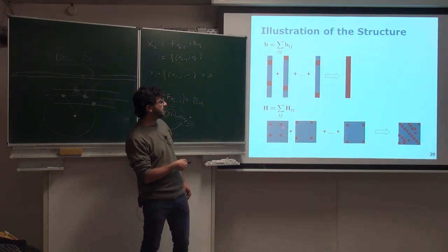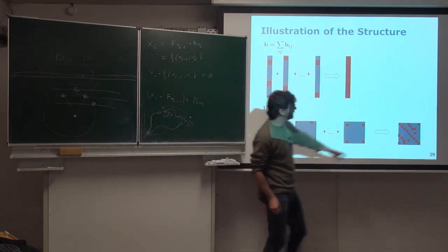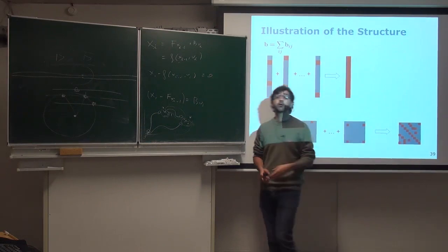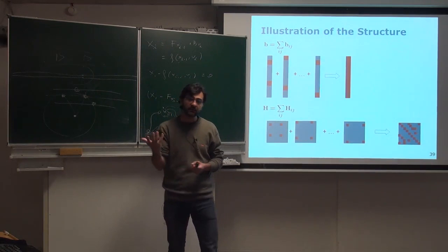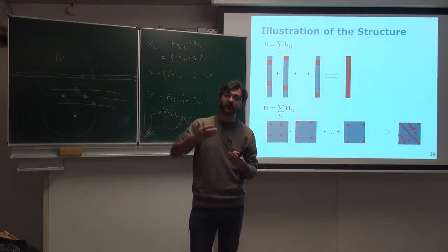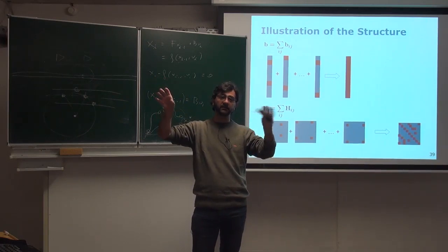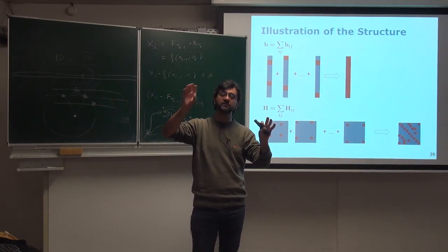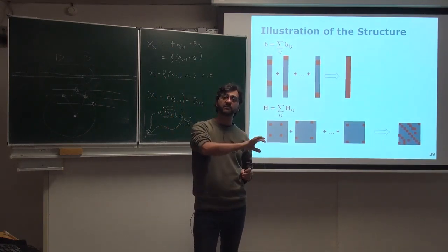What we end up with is a very sparse structure, and the interesting thing about this structure is that every off-diagonal non-zero element corresponds to one edge in the graph. Okay? And that's the relation between the concept of graph-based SLAM and least squares: the adjacency matrix of the graph actually has the same sparsity structure as the Hessian matrix of your least squares problem.